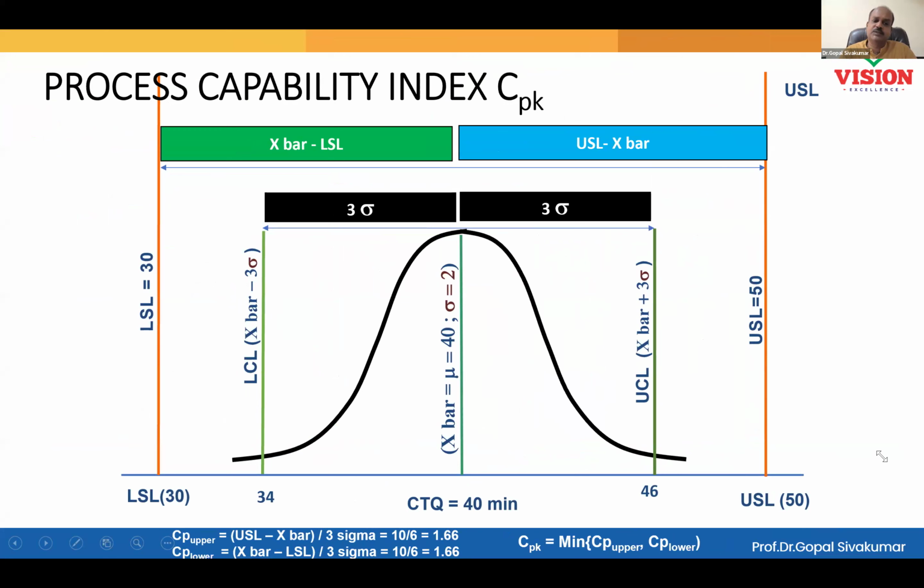Variation-wise also okay. Location-wise also okay. Great scenario. Your CP and CPK are the same in this situation. This is what is required.